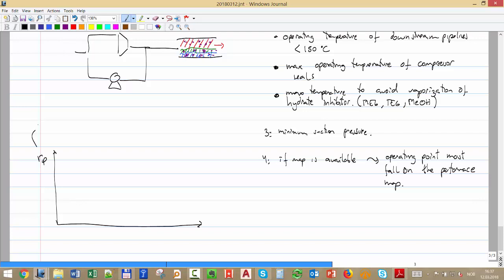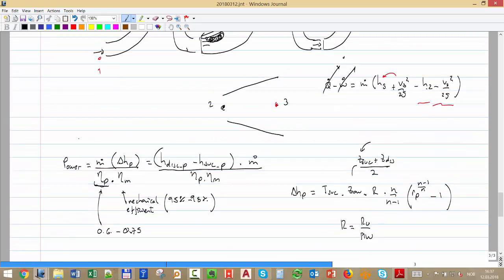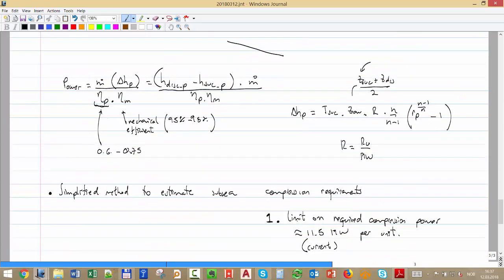It can also be the polytropic enthalpy divided by g, which I call polytropic head. But you already saw from the expression we gave before that it represents the pressure ratio. Okay, it's like another expression for pressure ratio.